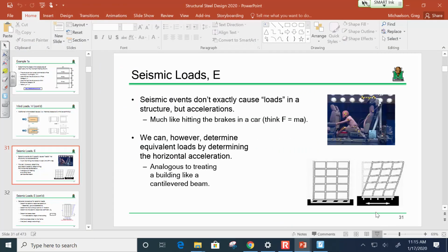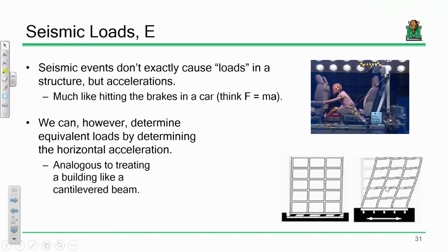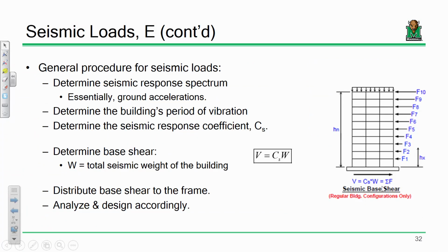Okay, so let's talk a little bit about seismicity and where that comes from and how we go about this for design. So if we're in design mode, we basically have to figure out how we're going to design the structure that's going to hold these loads up. And so, like I said, there is no earthquake monster applying forces to the building, but there is the mass of the building, and the building is undergoing an acceleration. So force equals mass times acceleration.